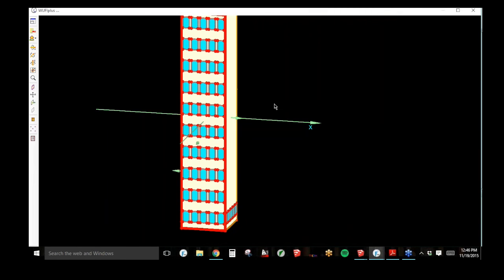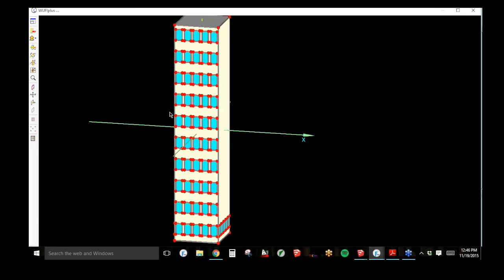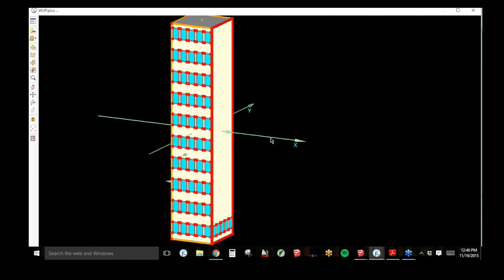I say okay, and now I have an additional like 45 windows, just like that. I think this is quicker than trying to draw them in SketchUp, assign them all in SketchUp, and then increase the import time as well. So I could go around and do this for each facade, but it's really the same.